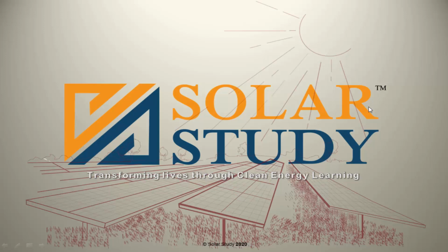In the previous lecture, we saw the module datasheet. From that module datasheet, we saw how to generate the solar IV curve for different irradiation and different temperature. There we used an inbuilt library called PVlib. Using that PVlib, we imported a module datasheet, a Canadian model of the solar datasheet. We added those values and generated the IV curve of that particular model.